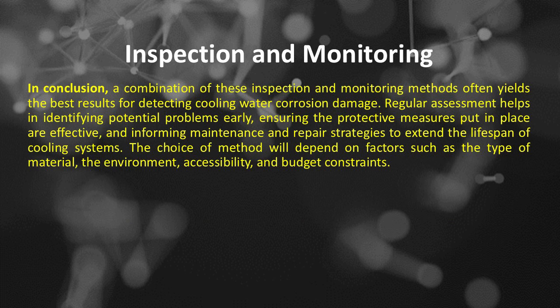In conclusion, a combination of these inspection and monitoring methods often yields the best results for detecting cooling water corrosion damage. Regular assessment helps in identifying potential problems early, ensuring the protective measures put in place are effective, and informing maintenance and repair strategies to extend the lifespan of cooling systems. The choice of method will depend on factors such as the type of material, the environment,